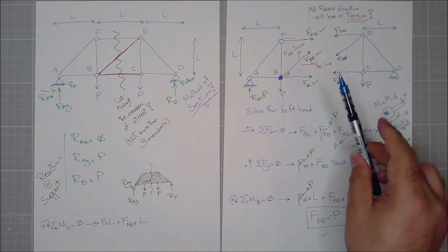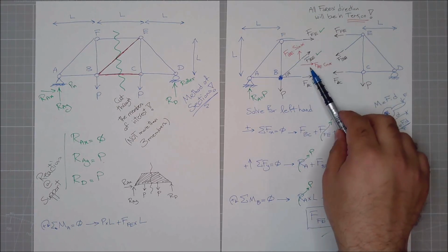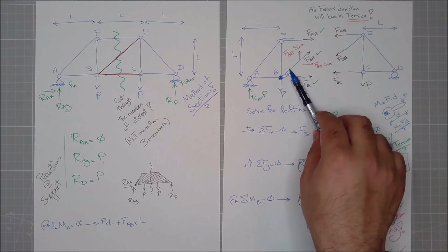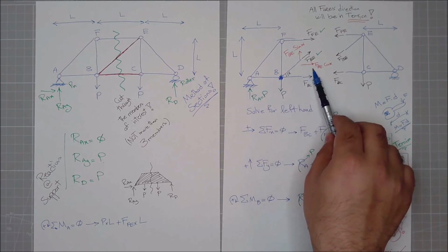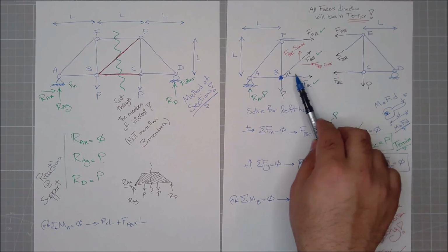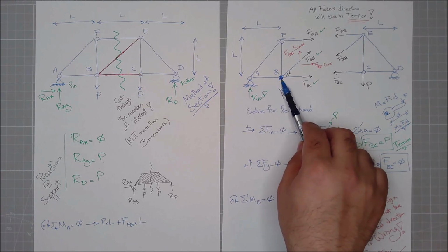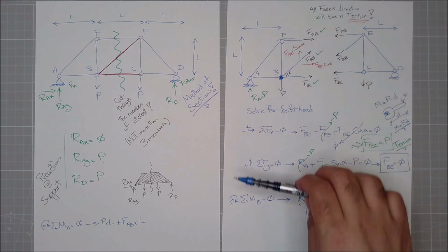and I will have this guy, because if I put the forces here, again we said doesn't matter where, but if it's here, the perpendicular distance of FBE cosine of alpha, the distance is 0 because the force is here, there's no perpendicular distance.